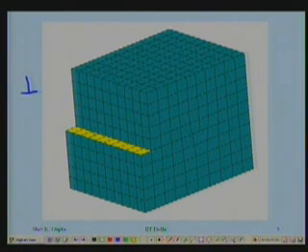And see, the number of planes in the top and in the bottom are the same, they are not different, but in here the same number of atoms are squeezed in with one planar spacing less. That's why you see these are in compression while these are in tension.